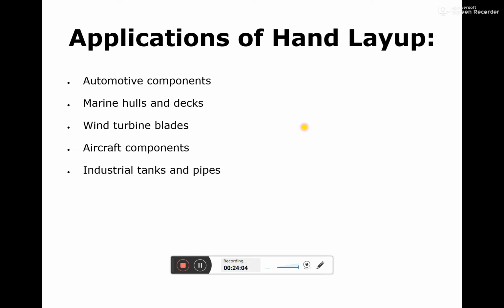In the oven you get curing at controlled temperatures, but sometimes people apply some load over the component taken out from the mold, for proper distribution of the resin into the reinforcement, in such a way that the resin material, that is the matrix material gel, is properly distributed into the reinforcement. This is what I discussed in today's class.